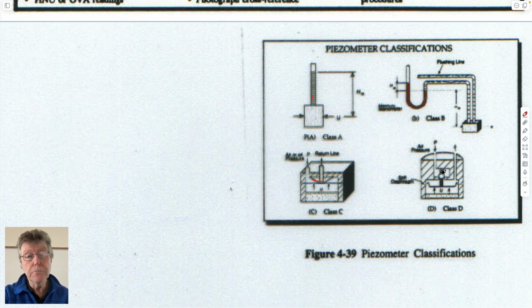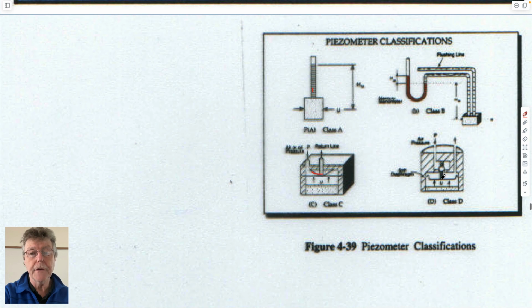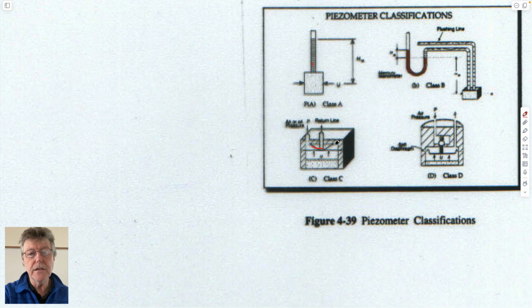And so electrical piezometers also have a membrane, but with a little strain gauge which measures the displacement of this membrane. And so the higher the pressure here, the larger the displacement. And so if you measure the displacement of this strain gauge, you can calibrate it against the magnitude of the pressure that you're applying. So all of these are ways of instrumenting your borehole to be able to usefully get some information from it.